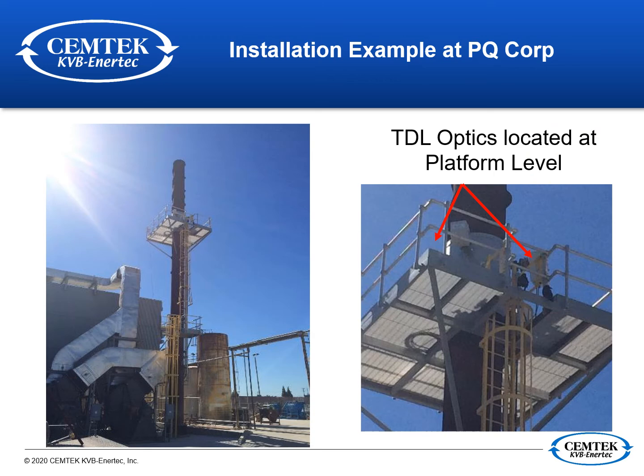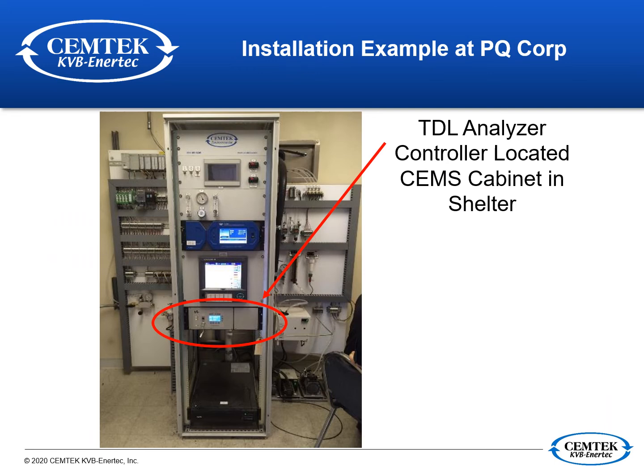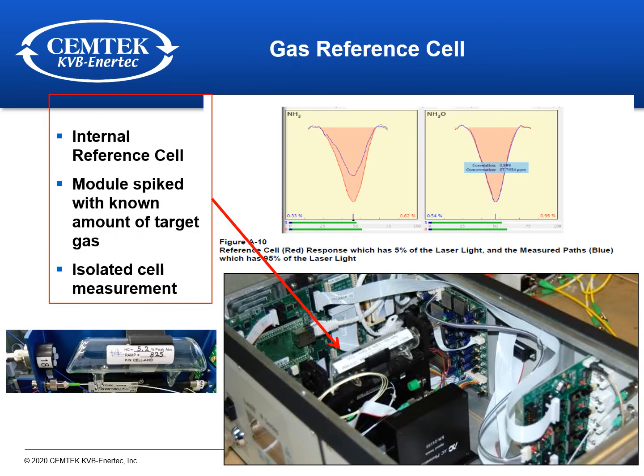Here is an example of an existing application. This is actually measuring ammonia for a process plant, a glass plant in Southern California. You can see up at the right-hand corner, you're going to have a couple of boxes for the monitoring of the ammonia, and the analyzer was placed at the base plant level. You can see where it's circled right there. Very simple installation, very cost-effective, immediate response time. Those are the big, huge benefits of this product.